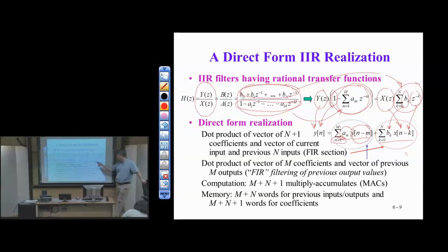So here it's tap delay line, x of n minus 1, x of n minus 2. The left-hand term is a delay line, y of n minus 1, y of n minus 2, and so forth. So it's just 2 for loops, down counting, multiply, add, and you add the two results together to get the final answer. So it's not too bad.